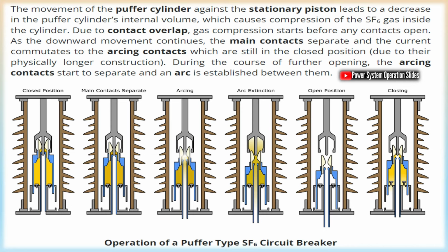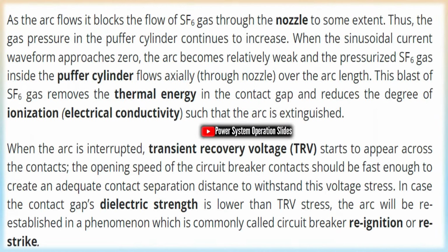Design requirements. In addition to the general characteristics normally associated with an electrical switch, i.e. low contact resistance when closed and almost perfect insulation in open condition, a high voltage SF6 circuit breaker needs to fulfill additional design requirements. Amongst these, the most pertinent ones are briefly described below.